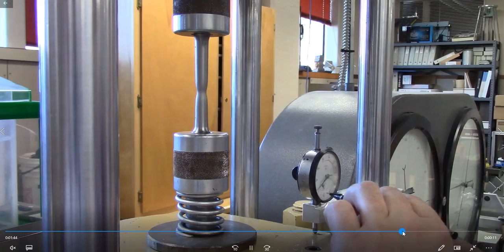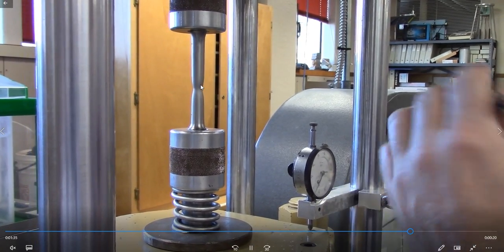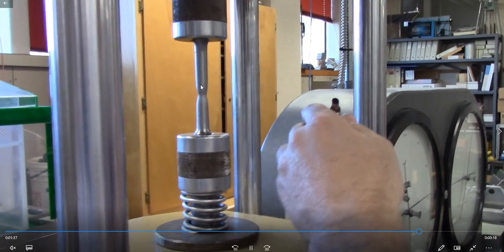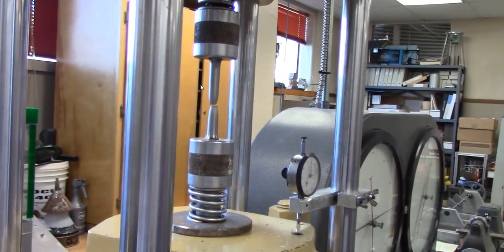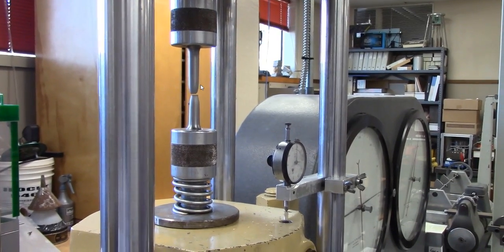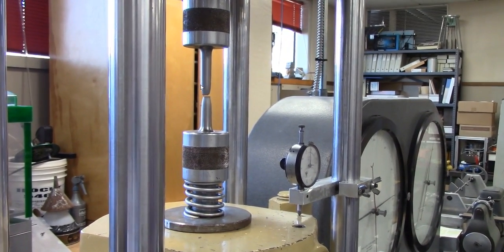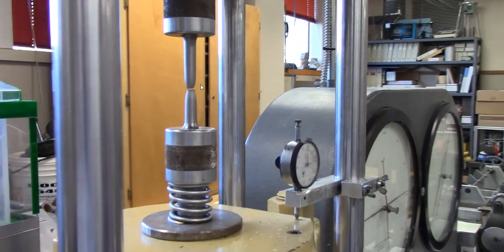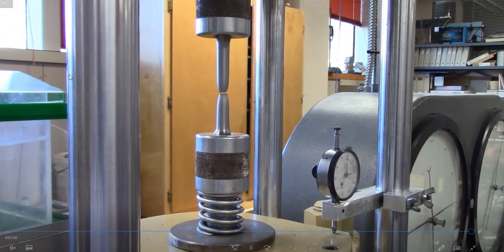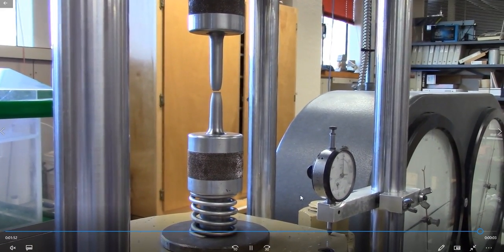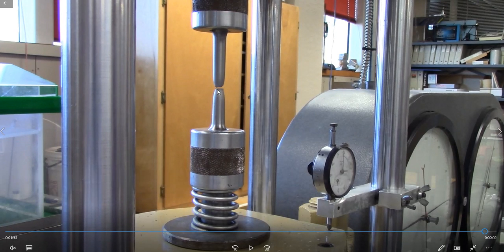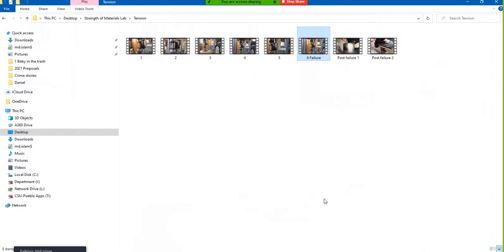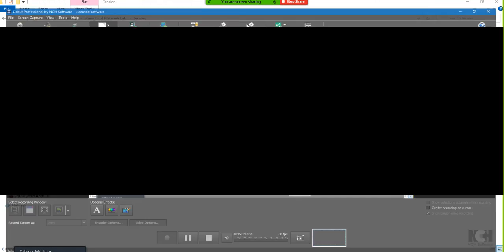I want to say that this necking was after the ultimate stress. After the ultimate stress, we can see the necking. But necking actually starts after the yield. After the yield, the permanent deformation starts, but we can see it very close to the failure. And then you can see that after failing, my cross-sectional area decreased a lot. Okay, so we will stop the theory discussion here. Now we will solve some